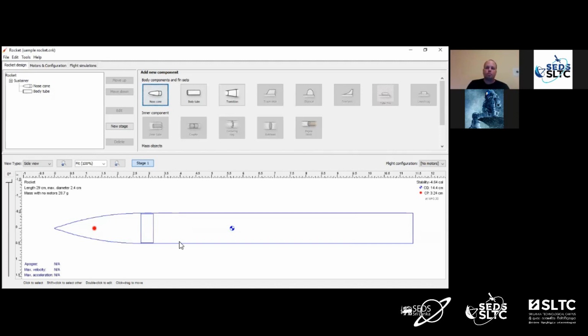If you recall from the last presentation, we need to have a motor mount. So our motor is going to fit into the rocket. We need to make sure that the motor can't push its way out forward through the rocket and actually shoot through the rocket, right? So we need a way for the motor to transmit its thrust to the rest of the main body rocket. We also need to make sure we have a retention going to the rear to make sure the motor doesn't eject itself out the back when the ejection charge goes off to pop the parachute, right?